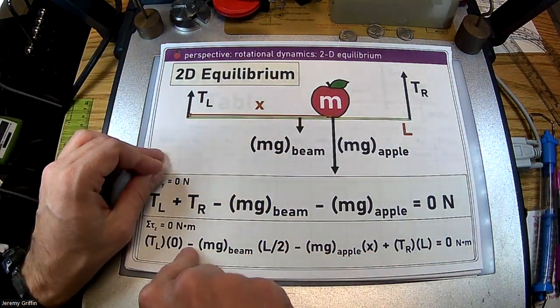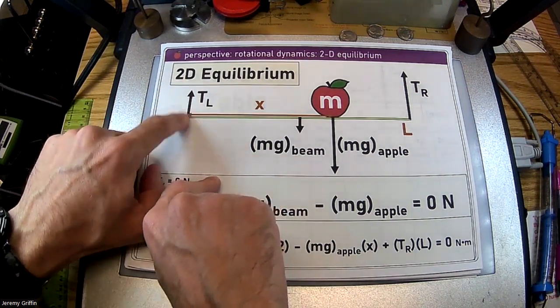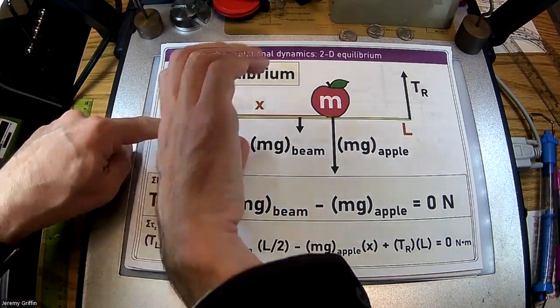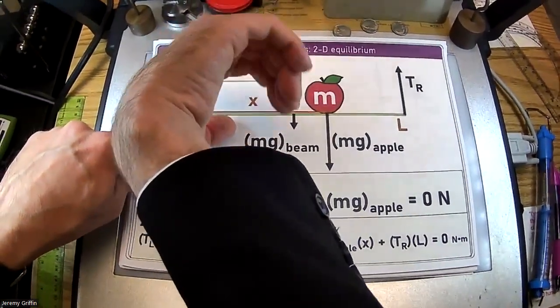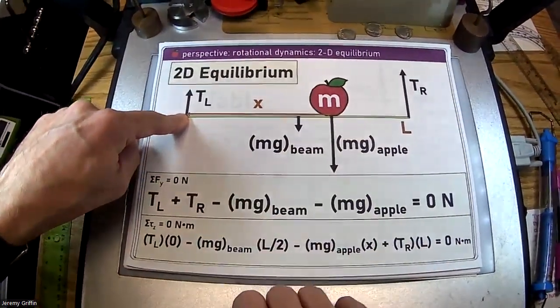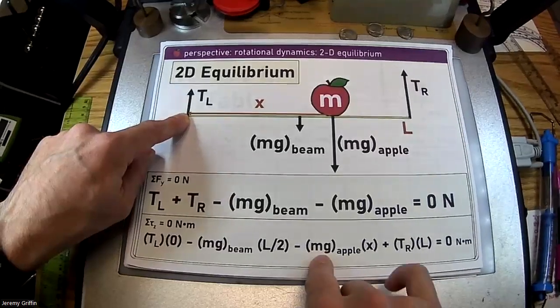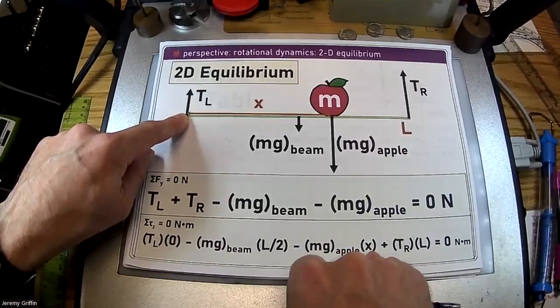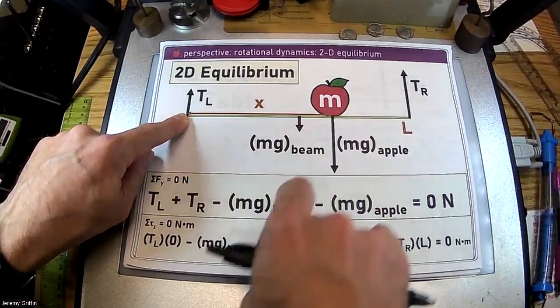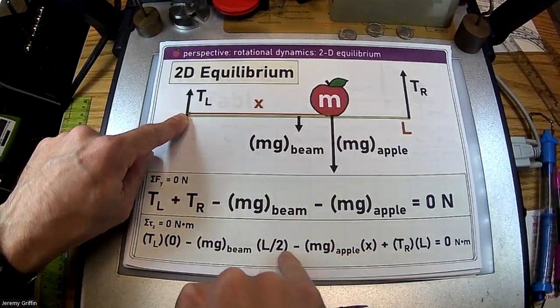It's negative because it's a clockwise torque relative to this point. If I treat this pivot like a door hinge, I see the weight of the beam is trying to make the whole thing turn clockwise from our point of view. The weight that's stacked on here is also clockwise. So here's the weight, here's some distance x. Here's R cross F, also clockwise, that's why it's negative.